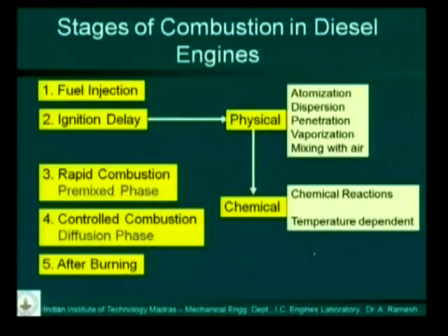Yeah. So I think you wanted to know the diffusion phase, right? So if you look at the fuel injection, when you inject the fuel into the combustion chamber, let us say we are injecting at high pressure through an injector, so the fuel comes as droplets and it goes inside. Now a liquid fuel as such cannot burn. Fuel has to vaporize, mix with air and then only burn. So the first drop which enters has to first vaporize, move out of the drop, go and mix with air and then burn. So this is something physical,